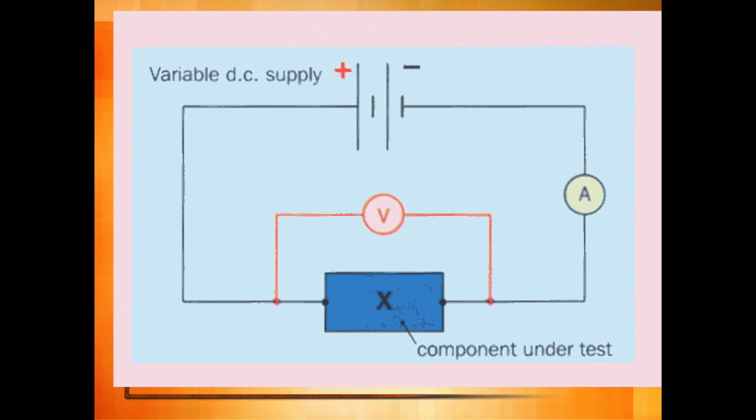Same thing with the ammeter, but in reverse. The ammeter needs the current to go through it. And so we want to have a really low resistance on the ammeter so the current can go through it, but it doesn't affect the overall resistance or the way that the circuit behaves.